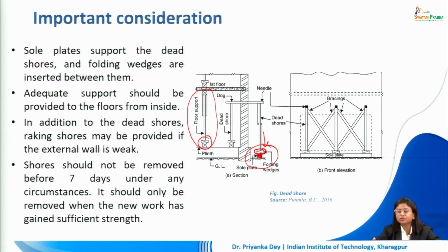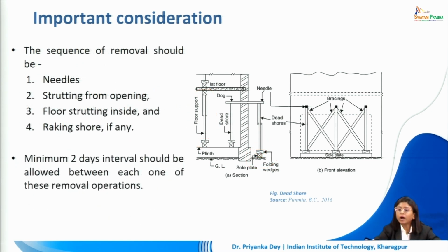Then we can start removing the different pieces supporting the floor slab from inside the room or the opening area, or the needles used to create this opening. Now, how do we remove this? We are going to remove the shores in a particular sequence. We first start with the needles. So that will be the first thing that will be removed.